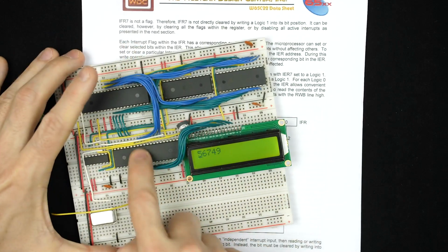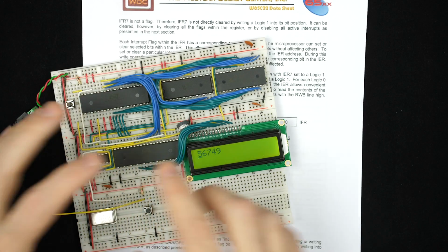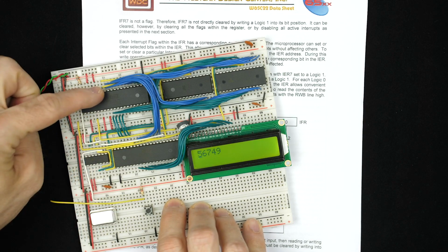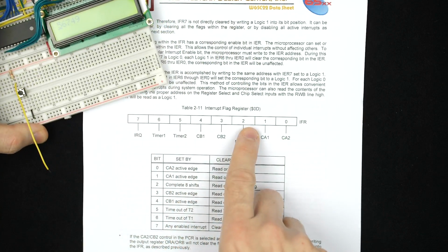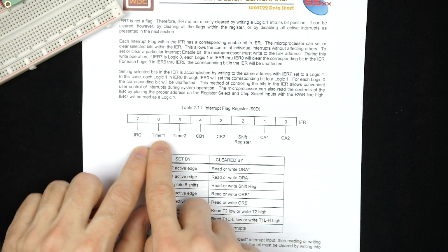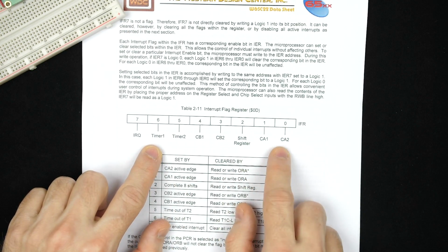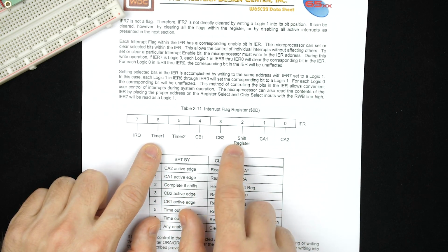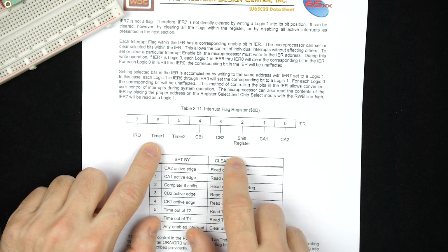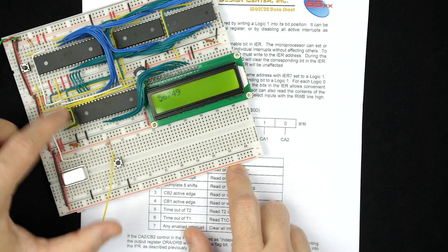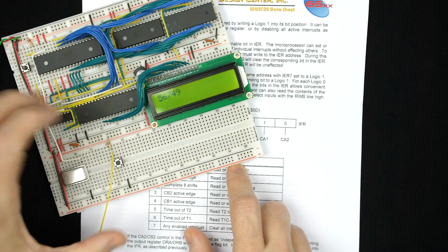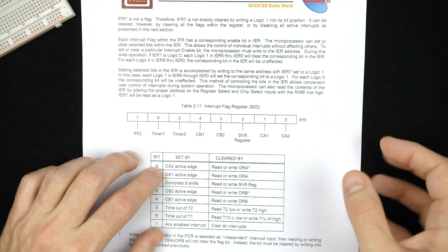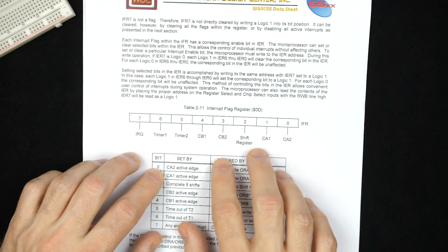So when the 6522, however it's configured, some kind of thing that creates an interrupt happens, it'll signal an interrupt here. Well, then the processor can then read this interrupt flag register to see what caused the interrupt. And you can see there's a bunch of different types of things that could cause the interrupt. There's some timers that we could configure. There's shift register functionality. If you're reading serial data in here, there's an interrupt that will trigger when the shift register fills up and there's more data to read. So there's a bunch of different functionality that's supported. You can read through the whole 6522 datasheet to learn more about that stuff.